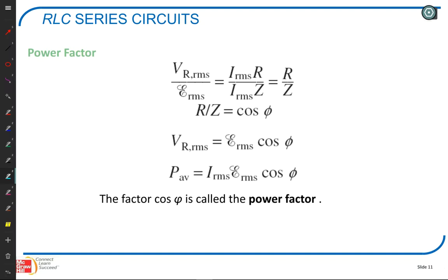And so if you have something that's a pure inductor, something like a fan is just an electric motor, which means you have a big old coil, an inductor, and you put electricity through it, and because of the external magnet, it makes it rotate. So the fan uses virtually no energy. It uses some energy to get started, and of course there's a little bit of energy to keep it going, but it's not using very much. But the current it's using is pretty high. And so the power company is just charging you for the current times the voltage.